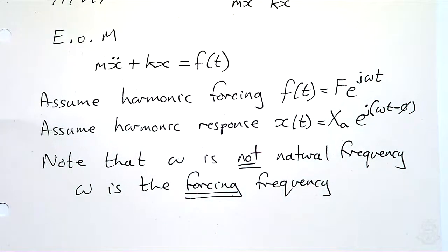So what does that mean in terms of the physics? Well, what it means is if you take a system like this and you shake it with a sine wave, it tends to respond at the same frequency you're shaking it at, okay? Whereas previously, what happened was it responded at the natural frequency or the damped natural frequency, okay?